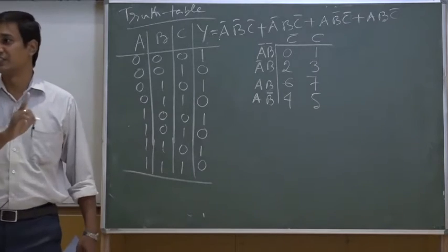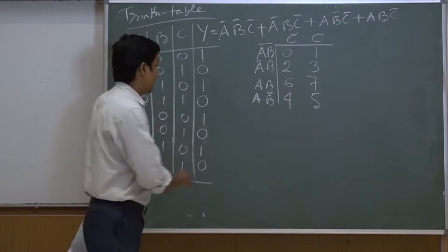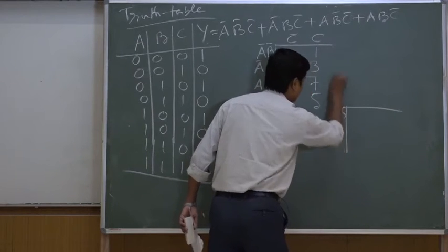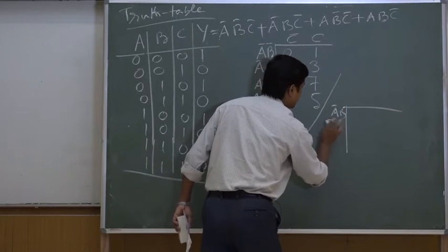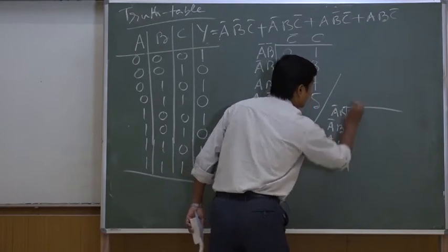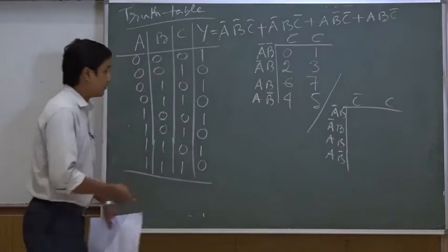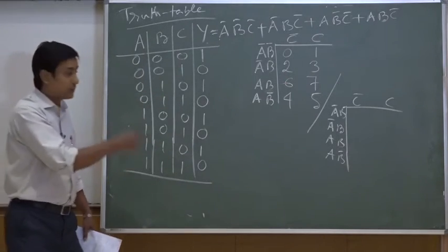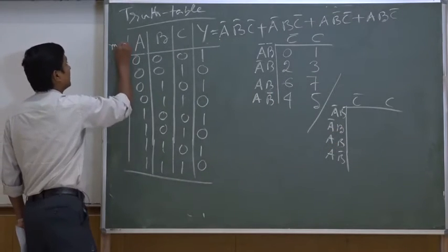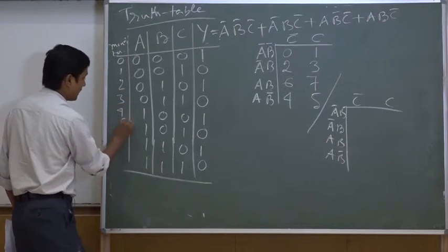These are the min term positions in the Karnaugh map of 3 variables. Fine. Now, if I want to place my truth table in this Karnaugh map, I would like to use the min terms which are 1 to place 1 in the Karnaugh map. So, let me find out which min terms are present: 0, 1, 2, 3, 4, 5, 6 and 7.